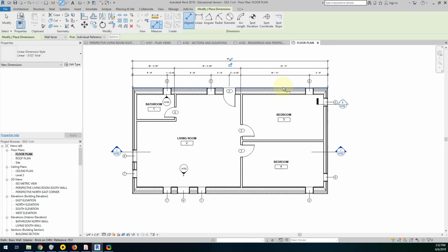Now we'll probably have to adjust the placement of our views because now these dimensions are there. So I start with the exterior of the face, the window, first instance of the wall, next window, outside face of the wall. These are going to get in the way of those lines there. Same thing, only the walls and the overall of the floor plan.